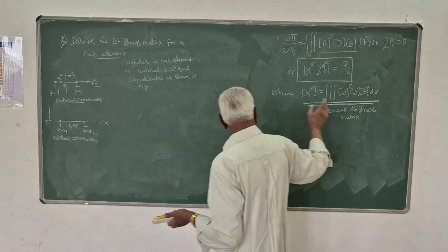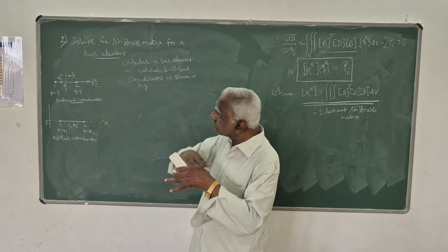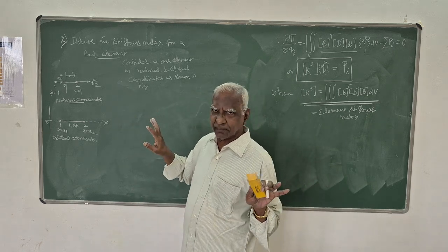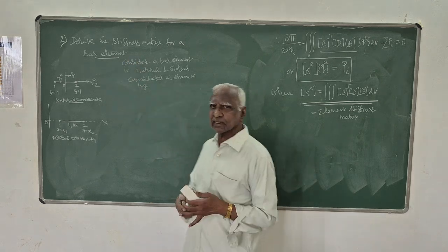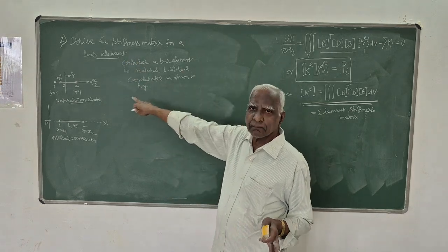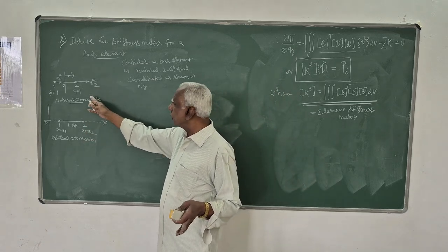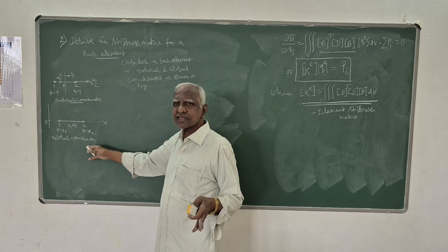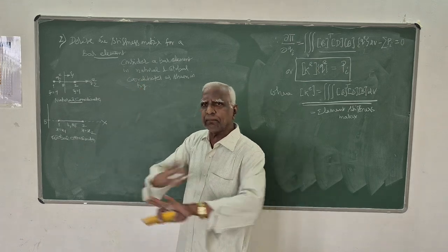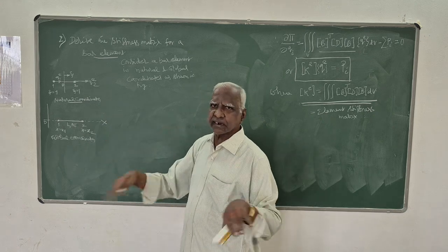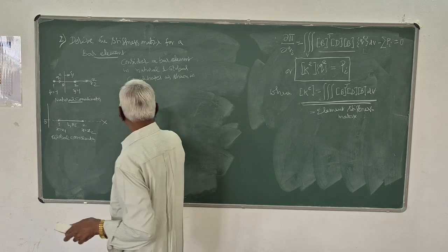So I have derived a general stiffness matrix equation for a general isoparametric element. Now I am specifically deriving that same equation for a bar element. It has been shown both in natural coordinate as well as global coordinate fashion. Strictly speaking, it is an isoparametric element. So all finite elements, we can treat them as isoparametric elements, as shown in the figure.